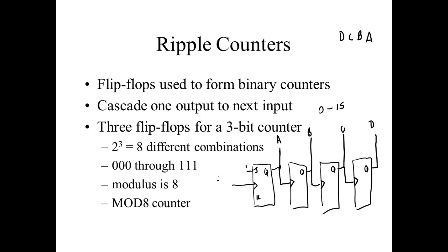So I come over here, and this is edge triggered, let's just start off with all of these equal to 0. No, these need to be low active, sorry, like a 7476. So we start off, and on the low going edge, this one goes to a 1.